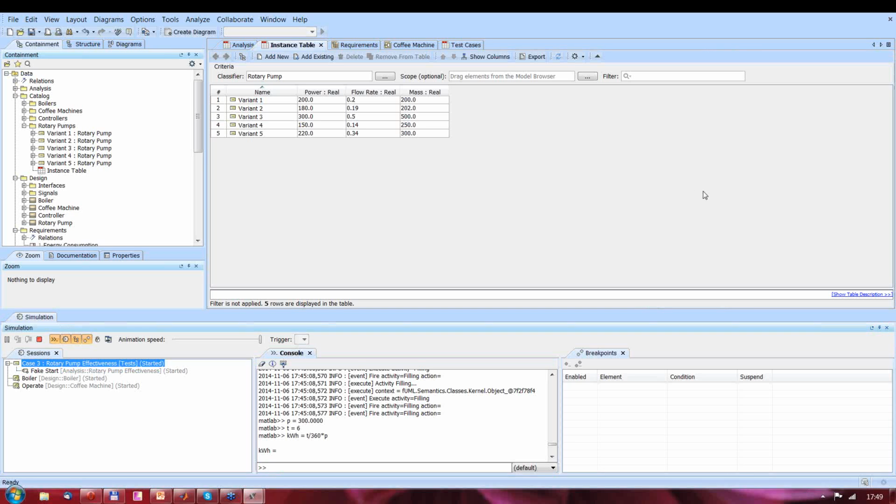Well, actually, in this example, if I understood your question correctly, the state is not referenced, but it is possible to check what the state is, to add a constraint, for example, that would check what the state of the block is. There is an action language helper for this called inState, and so then you can check in what state the current block is, and use it as the condition, as the constraint, or whatever.